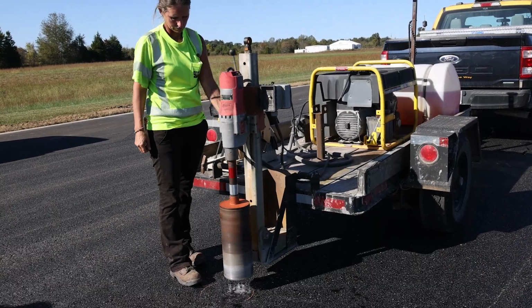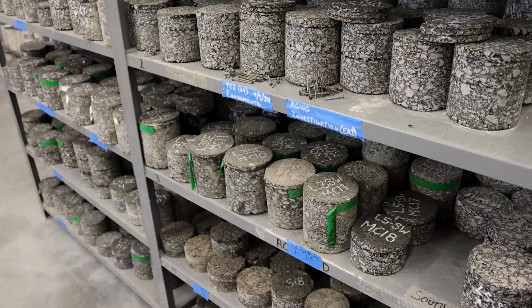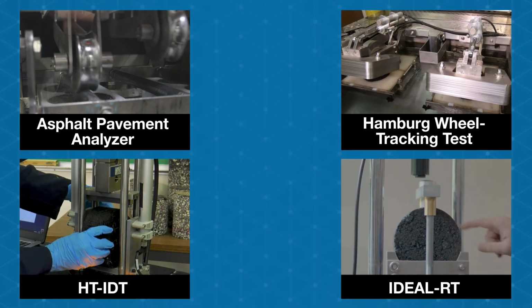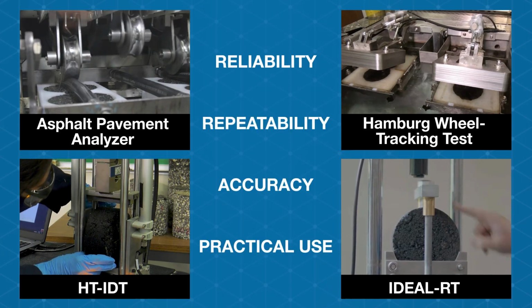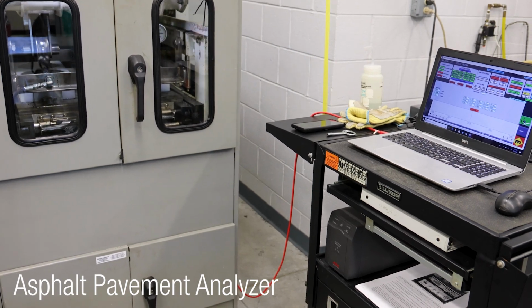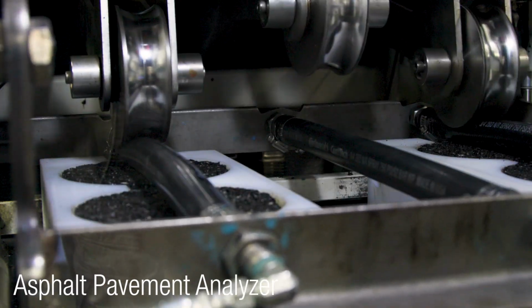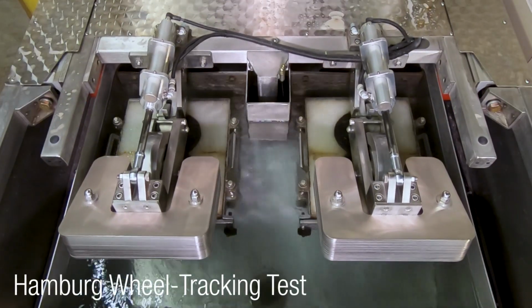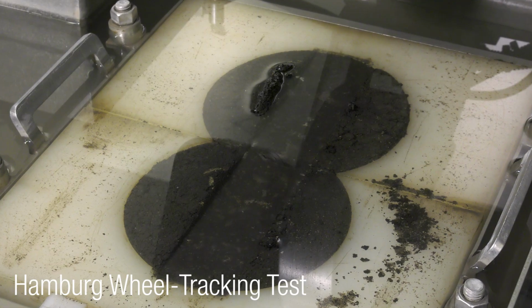The team collected asphalt samples from active airfield projects across multiple states, representing a real range of materials and production conditions. From there, they evaluated 4 test methods for reliability, repeatability, accuracy, and practical use. The Asphalt Pavement Analyzer simulates repeated wheel loading under dry conditions at 2 pressure levels that reflect the range of airfield loading. The Hamburg Wheel Tracking Test evaluates rutting and moisture susceptibility under submerged conditions and has a strong track record correlating with field performance.